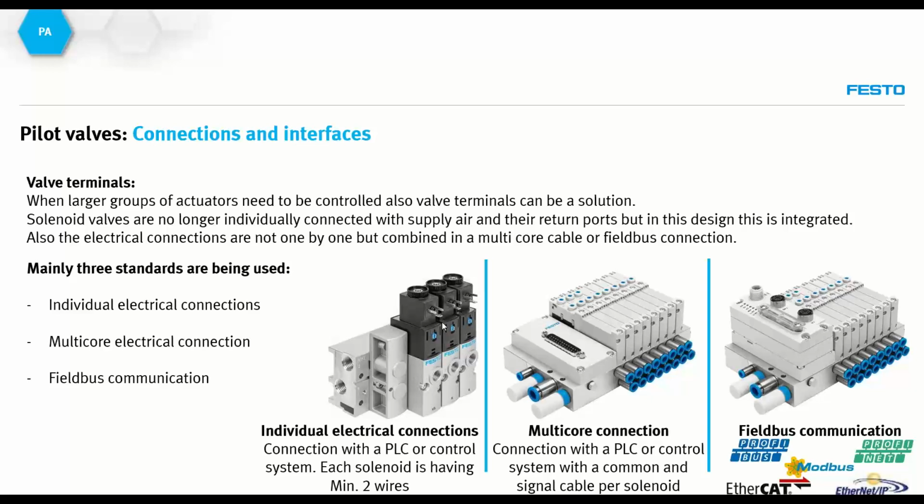But for larger applications where more valves are used, this is already a very good step forward. This avoids placing a lot of different solenoids within the certain parameters of the pneumatic actuators needed. The only thing is more wiring is required because each and every solenoid valve has at least 2 to 3 lines to be connected with the PLC, which means more PLC outlet cards are needed.